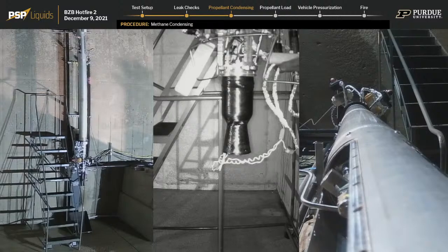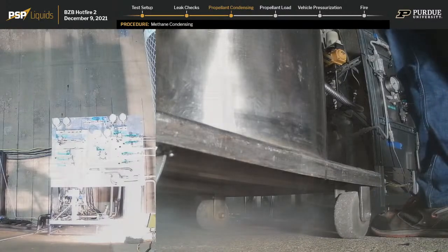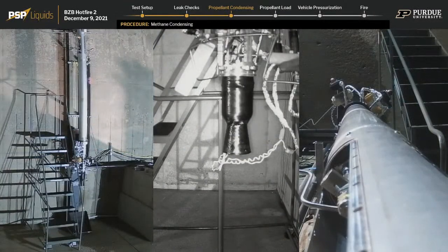It restricts the amount of time we can get out of the engine for a certain pressure. And it would also likely drive us away from a pressure-fed system because of the large pressure losses associated with flowing through a regenerative chamber.